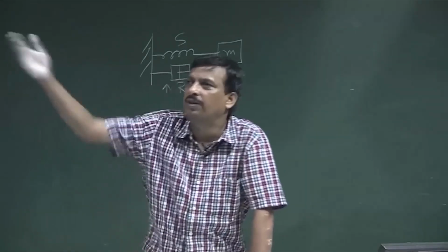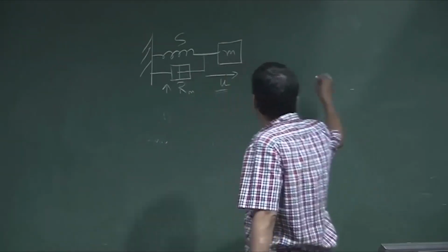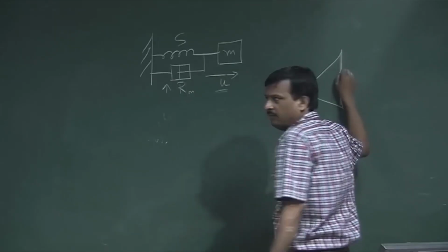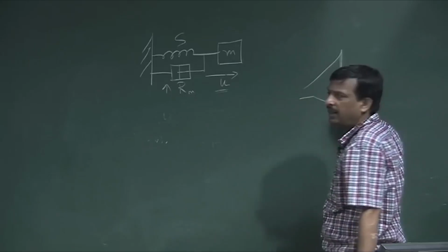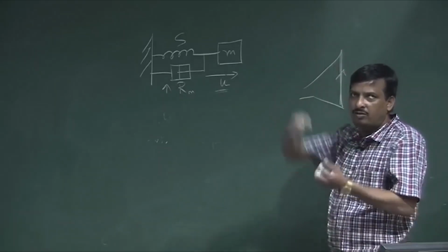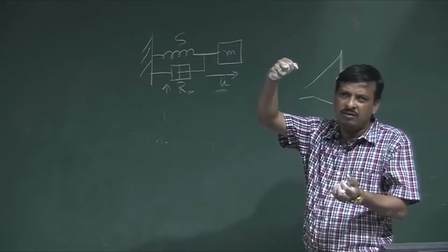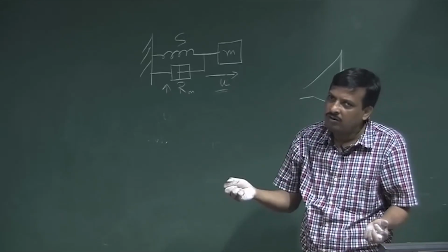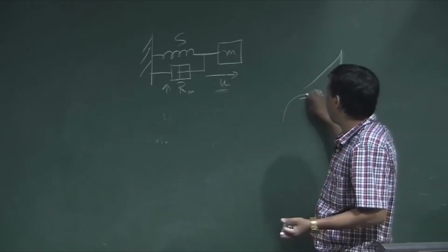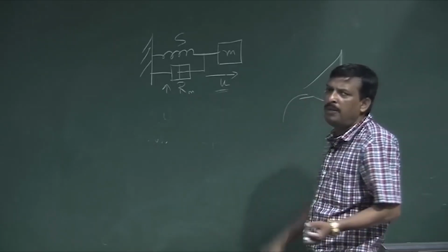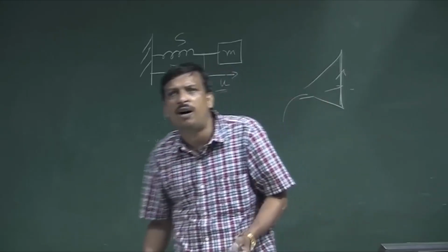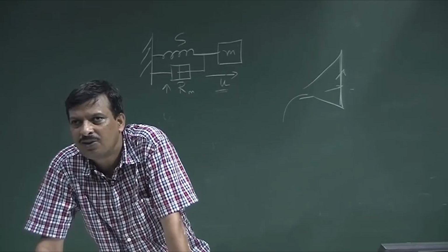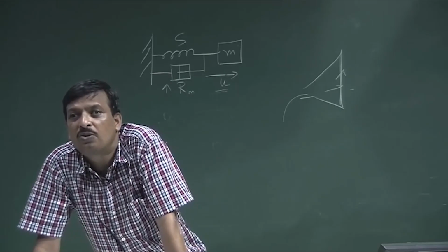Think about the loudspeaker. The loudspeaker has a membrane, a diaphragm. The diaphragm is nothing but a mechanical system. It is suspended on a cage, so it has a tension, it has a mass, and it has a damping factor also. Now, if I apply an electrical signal, I want that membrane to vibrate as per the electrical signal frequency. So, that is called forced oscillation.